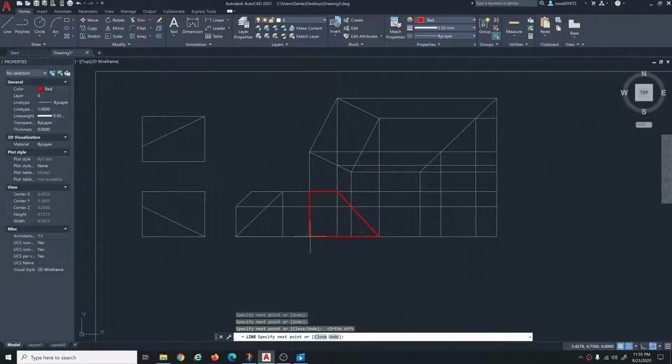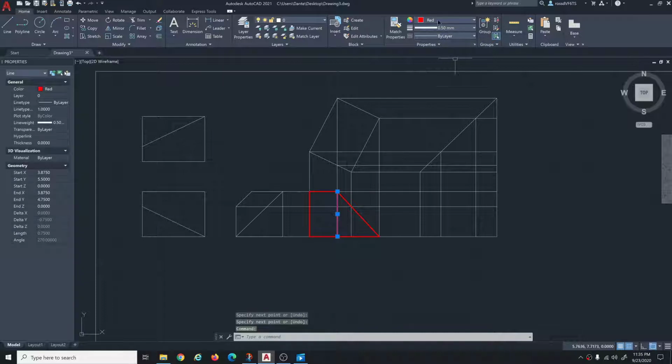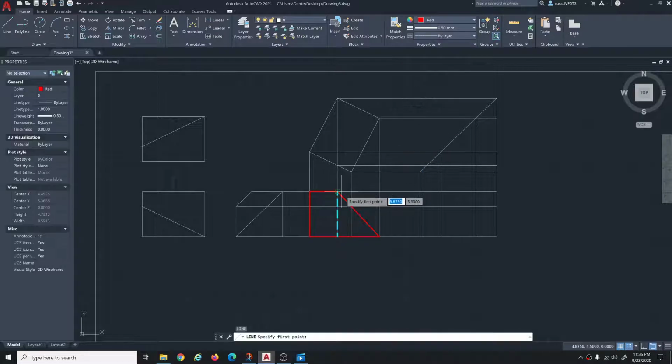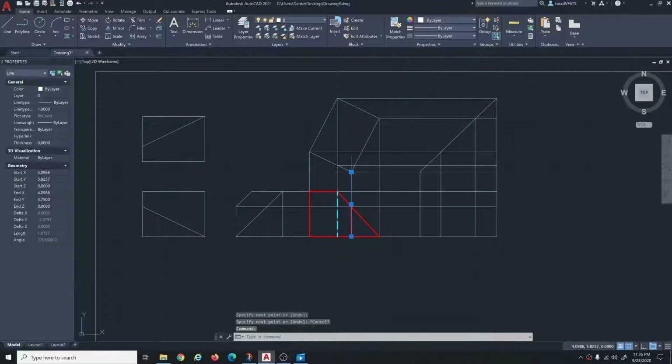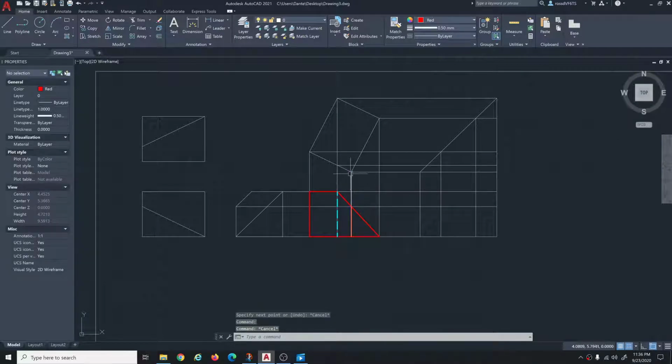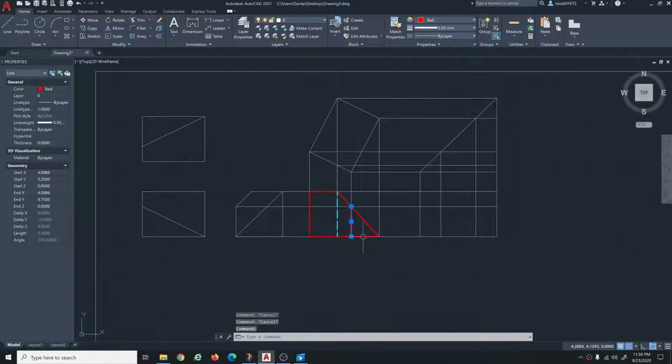And across the bottom, then there's going to be a line here that's going to be hidden because that's on the back side of the object in the top view. And I'll change that to hidden while I'm thinking about it. Then there's going to be a solid line right there. That's this point right in here, which in the top view is a line going down, perpendicular to the paper, if you want to think about it that way. Shows up as a straight line here, and that's that view.